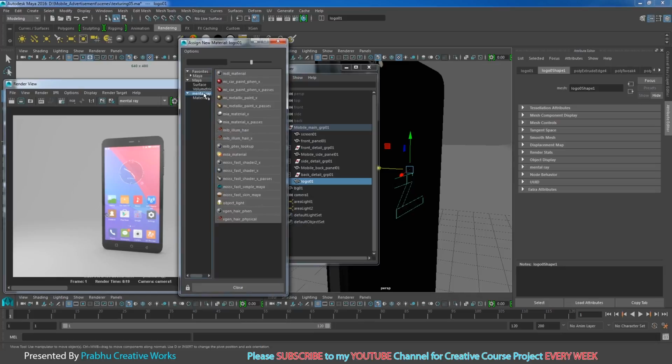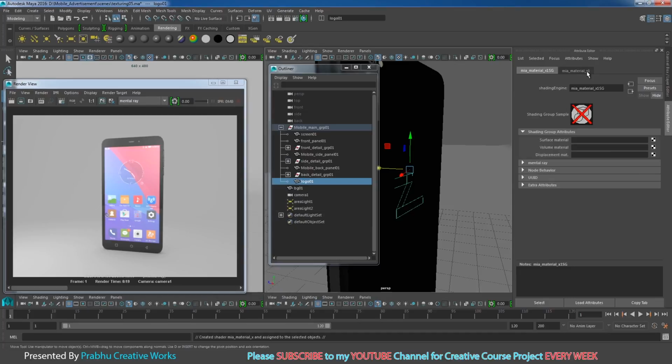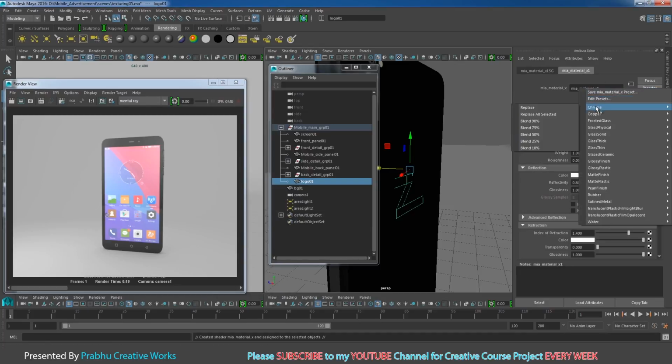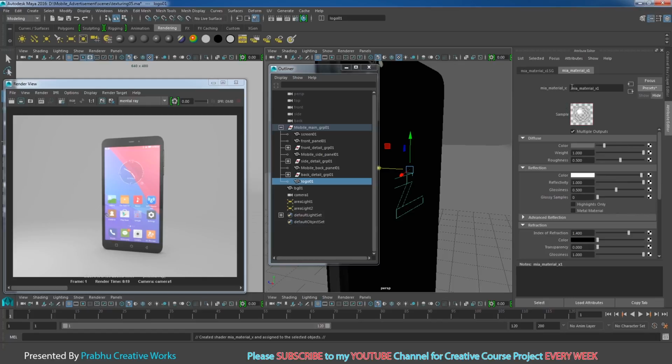I will go to mental ray and choose Maya material X. In Maya material X1 you want to go to preset and choose chrome and choose replace. Before that, I want to rename Maya material X1 as logo underscore Maya material X1, and press enter. Like this.